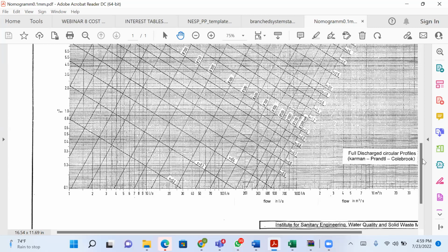Unfortunately, I didn't have the surveyor's parameter to know the elevation, the slope between the water source and that point at the beginning of the street, right? I don't have the parameter, but let me assume that it is about 0.2%. Now, 0.2% is the same thing as 2 per mil.